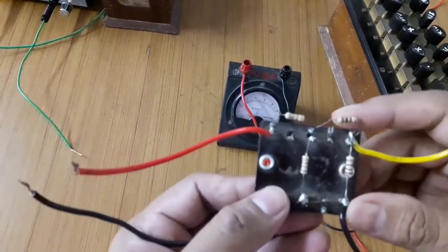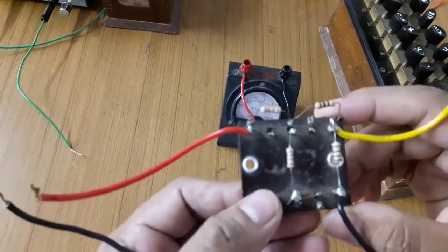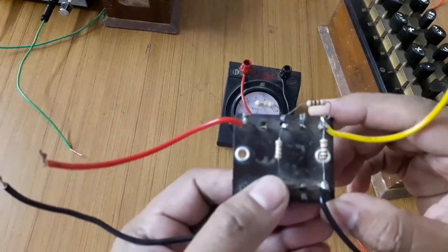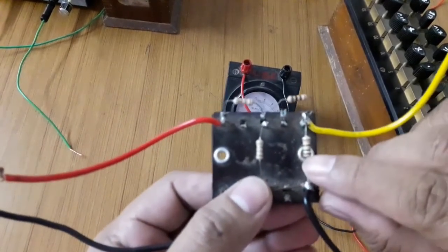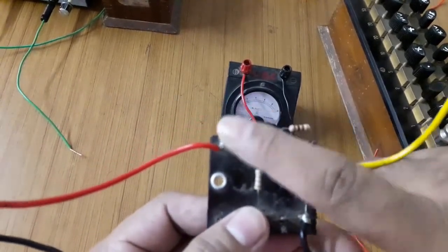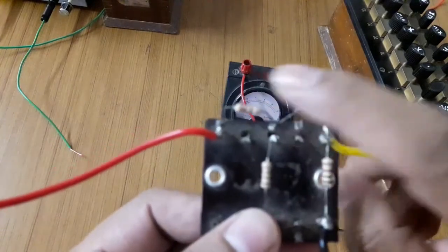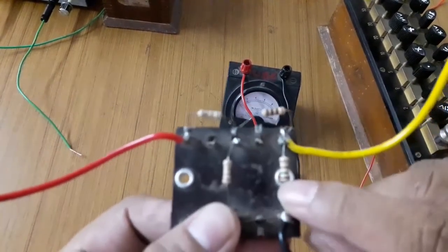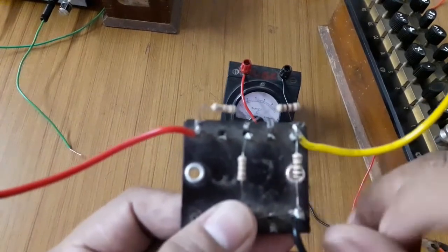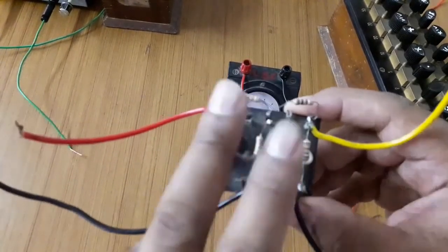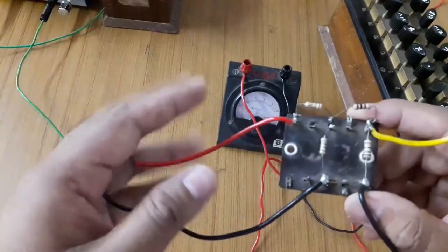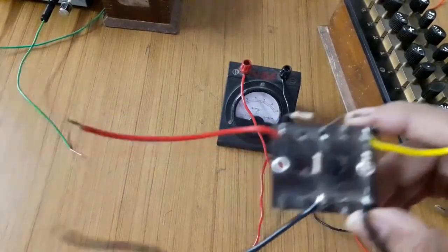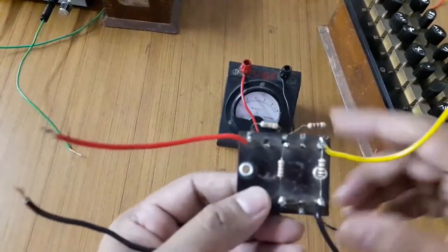Okay students, we are ready for performing our experiments, and as you can see, it's the same circuit that we had used for Thevenin. We have 150 ohms over here, and these three resistances are 100 ohms each: brown, black, brown, and this one is brown, green, brown. We have already done the calculation for the equivalent resistance and the Norton current in the first part, so we will perform this in the second part.